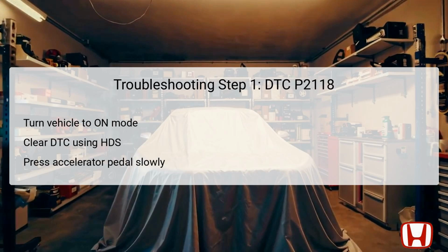The first step in troubleshooting DTC P2118 involves verifying the problem by putting the vehicle into the on mode, a state where the electrical systems are activated without starting the engine. It's critical to utilize the Honda Diagnostic System, HDS, to clear any existing DTCs, including P2118.